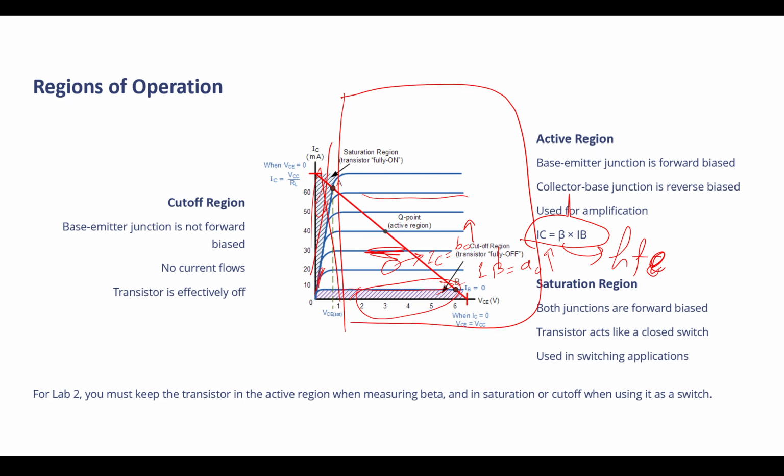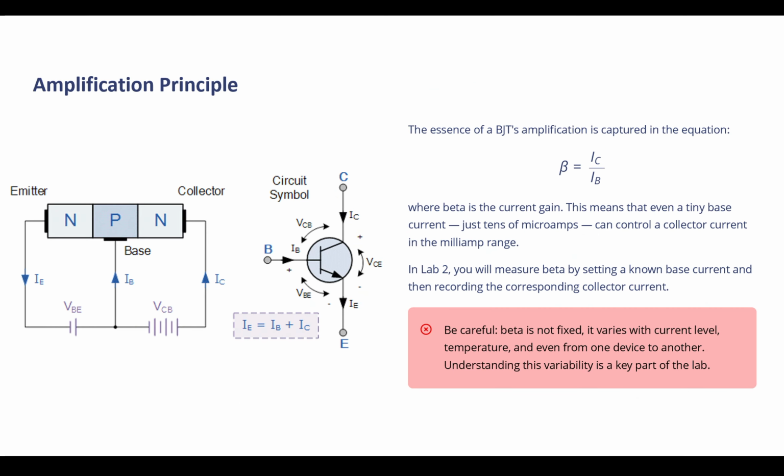That little behavior gives us the ability to use that BJT as an amplifier. So you inject a very weak signal into the base, and normally BJTs have a beta of over 100 to 200. So you are going to get a very amplified version of your weak signal at your collector. Make sense? Now, in eLab, we are going to talk about this amplification and actually build those amplifiers. So for now, just remember the concept.